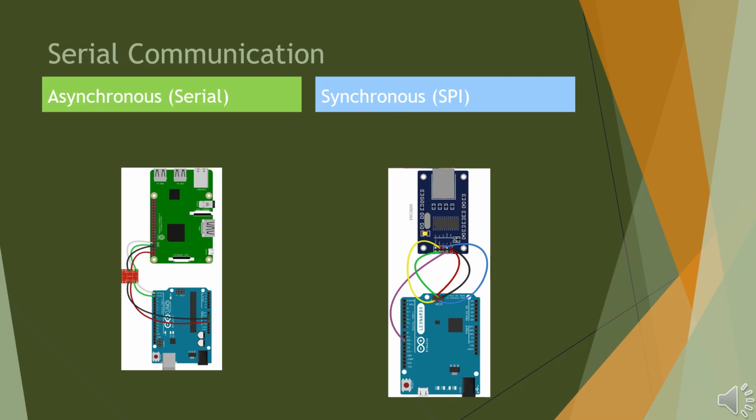In this example, the Arduino Leonardo connects to an ENC28J60 Ethernet module, but the same wiring applies to other SPI devices, such as temperature sensors, flash memory, or displays. SPI is a synchronous full-duplex protocol that uses a shared clock signal for timing and consists of 4 key lines: